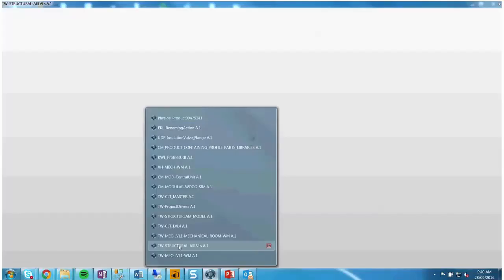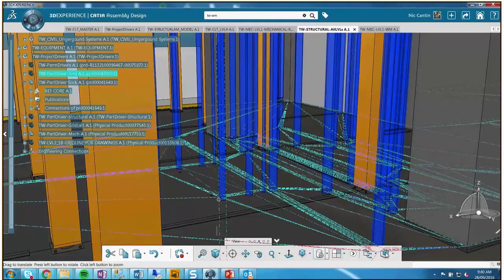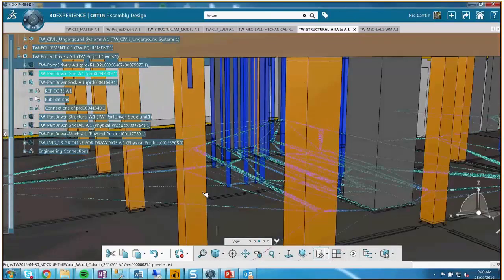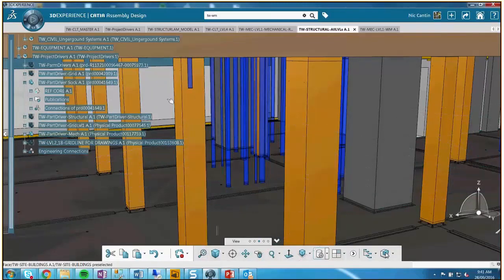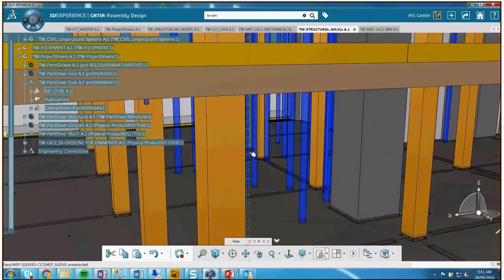How much repetition was there between the panels? There was quite a bit. I mean, 3 to 8 is typical, and then at 9, the way they designed the risers, there are no penetrations, so that was a different floor. And then the sizes from 9 to 17 were different in terms of the penetration, so they were slightly varying in that sense as well. But overall, I want to say 54 different panel types.